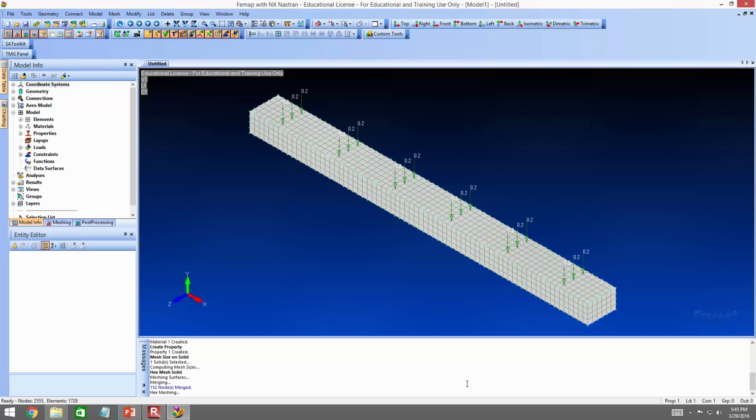You can see it broken up into those individual regions. Remember how the finite element method works. We're guessing what the solution looks like in between those elements. For an element like this, we're using linear interpolation. So the more of these elements that we use, the better our answer is. Make sense? We now have everything necessary to run the model. So what we'll do, we'll go to Model, we'll go to Analysis.